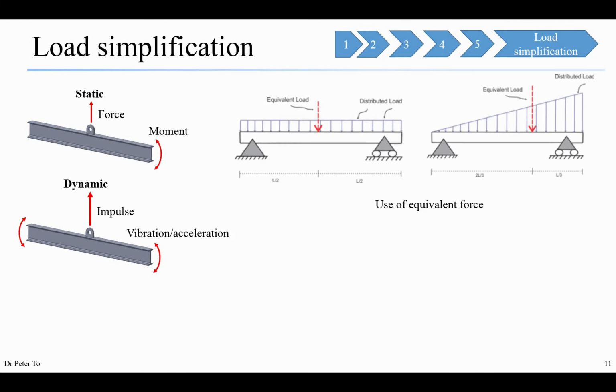In dynamics, we have the typical equation Ku + m d²u/dt² = F(t). Please remember that for explicit analysis, as in tutorial number 9, the time step must be smaller than some value so the simulation can converge. And for implicit analysis, you can use Crank-Nicolson, central time, central space, or other methods.